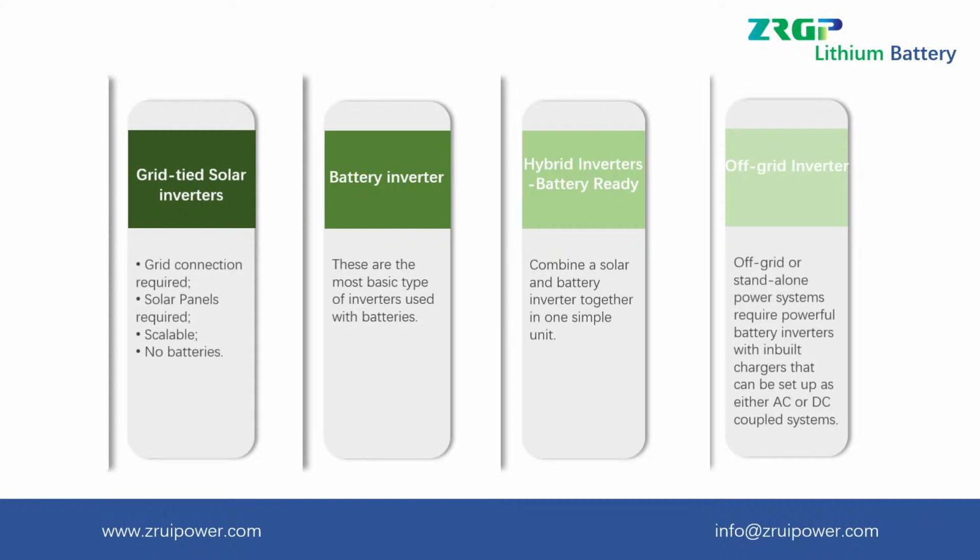The last one we discuss is the off-grid inverter for a standalone or off-grid solar system. Off-grid inverters convert the DC energy from a solar battery or the solar panels into AC energy. Some off-grid inverters work as inverters or chargers because they also allow you to charge your battery bank from an AC source such as a generator. These inverters are ideal for game lodges, rural areas, or a new home that is not connected to the grid.